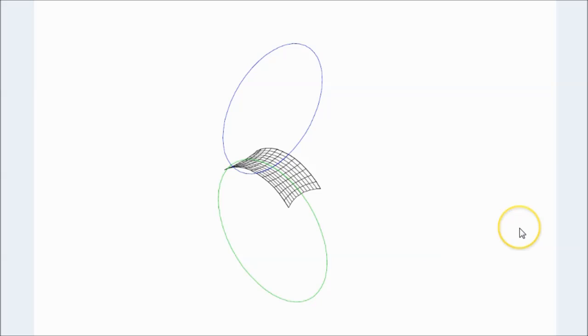A low pre-stress results in a structure that will deflect more with loads, but can be built with a weaker material and supporting structure. The key point is that whenever an external load is applied to a tensile structure, it will increase the fabric stress in one direction and reduce it in the other. Note that fabric stress is always measured in lineal stress, which is pounds per running inch. 2 pounds per inch is a common pre-stress value. Now let's talk about how to estimate structural stresses.